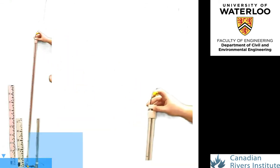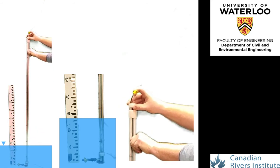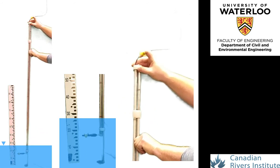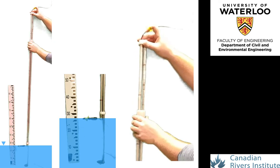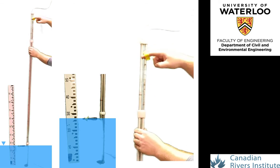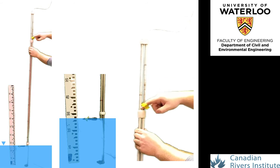Let's repeat this process for another flow depth, in this case 27 centimeters. First, the sliding rod is adjusted until the center line of the flow meter axis coincides with the water surface. The number of hatches are counted down from the top of the large diameter depth gauge rod: 5, 10, 15, 20, 25, and proportionally a bit more, which is the estimate to 27 centimeters. The depth is called out to the second field person to be recorded.